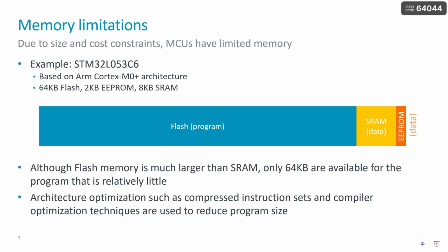Now, you have to consider the fact that the STM32 controller that's based on the Cortex M0 Plus architecture is used for instance in wearable devices, where I would like to save size and energy. In this situation, when we program it, we need to consider the fact that the instruction memory available is limited to 64 kilobyte. I'm not gonna write code that will be more than this. Other than this, I'm gonna get an error.